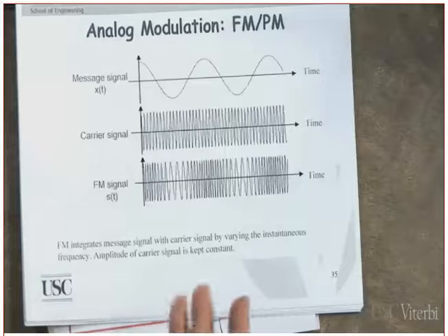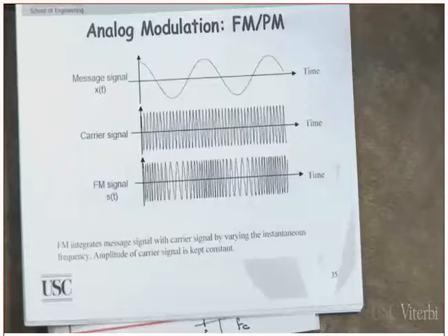The big issue in the design of RF is what is known as the intermodulation components. The reason is that harmonics usually are located out of band. Do you agree or do you not agree? If your carrier is F sub C, what is the second harmonic? 2F sub C. Chances are 2F sub C is out of band, which means any filter can get rid of it. Clear? But intermodulation components, especially the third order intermodulation components, we don't know what that means yet. We'll get to it shortly.